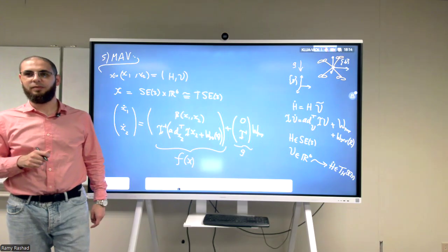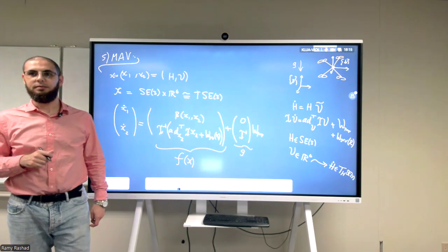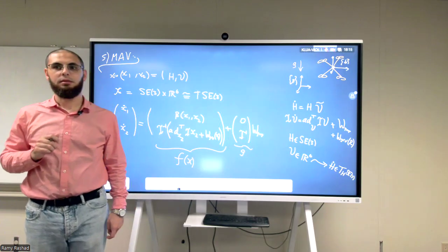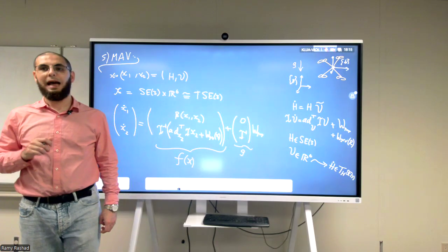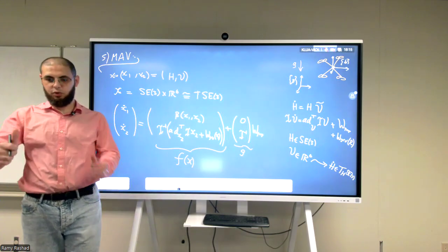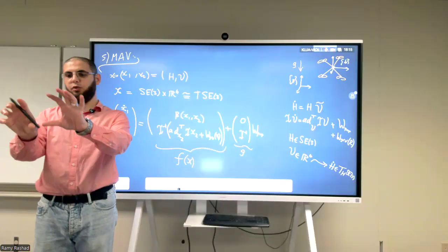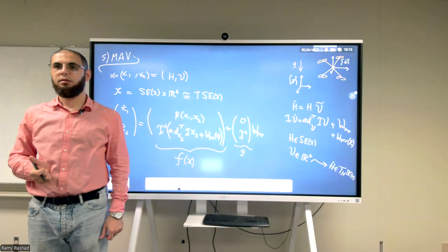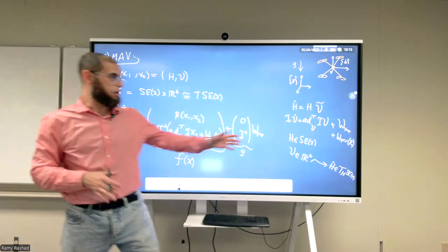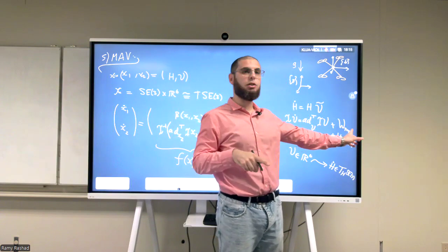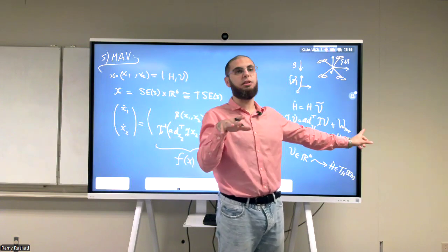Also, what about the tilt of the propellers? Will it affect the wrench? Active tilting or passive tilting? Passive tilting. You just take the propeller and make it point differently with fixed angles. Yes, the map that goes from the individual thrusts to the total, resultant wrench will be different.